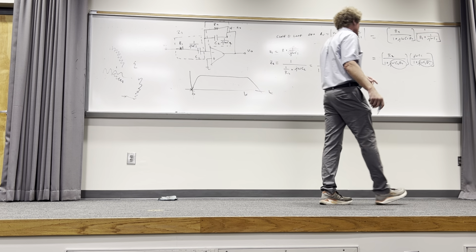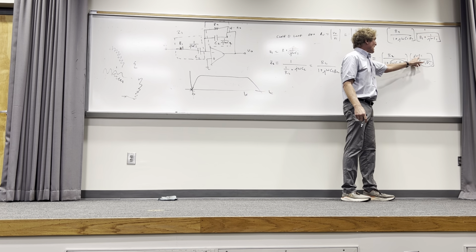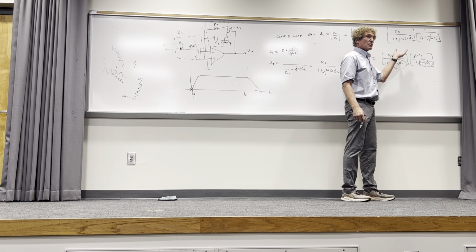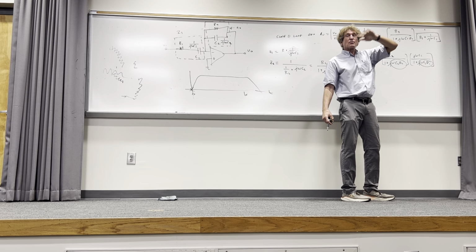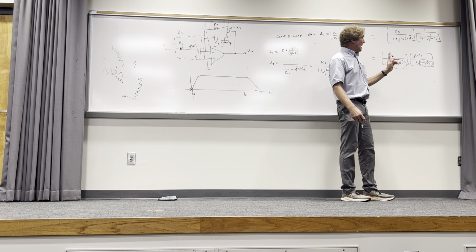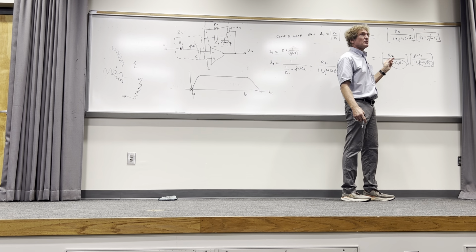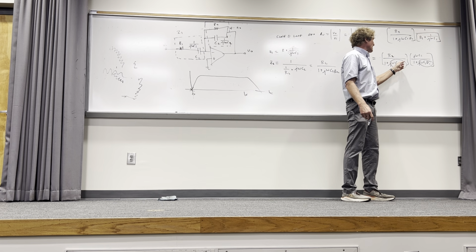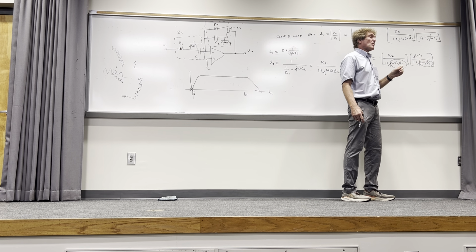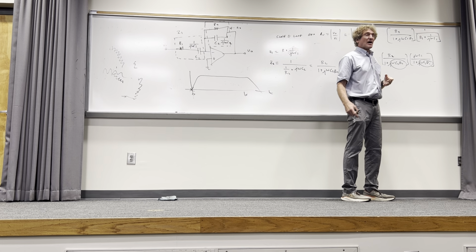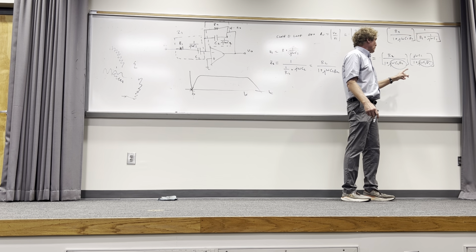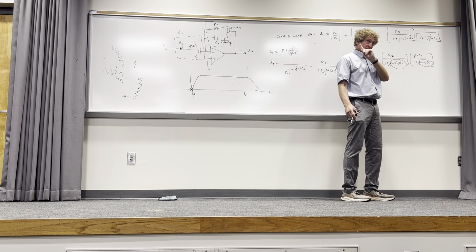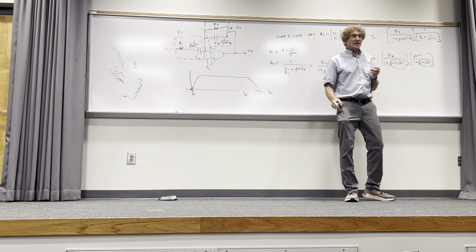In the very beginning, you're going to have omega C1 R2 as the weight upstairs. So as you increase omega every decade, it's going up 20 dB. Follow me on this? How many do? You know it's going to linearly increase. You can't help it. Downstairs, neither one of these two values, the omega C2 R2 and the omega C1 R1, will turn on. They will not be of the order of 1 and affect things until you get past these break frequencies, right? Now listen carefully. So it's going up at 20 dB per decade.